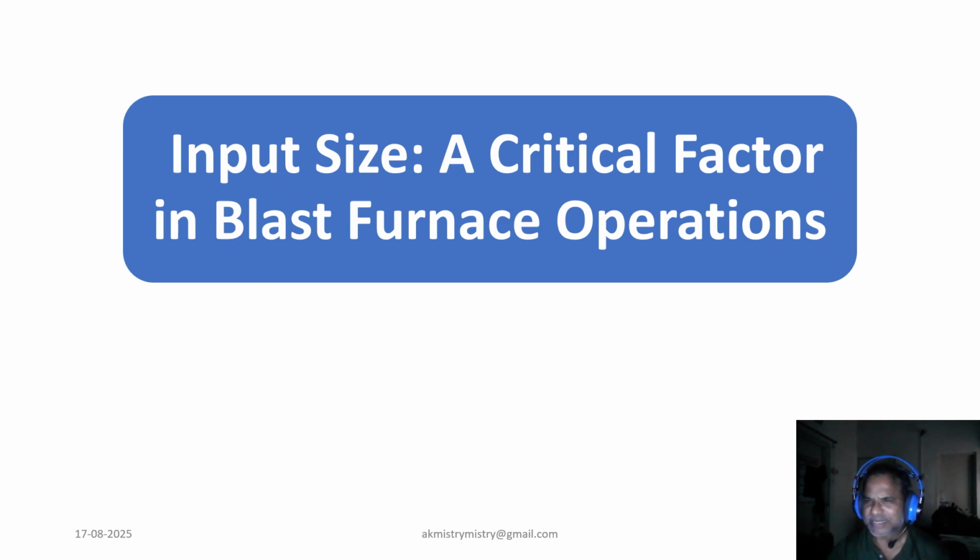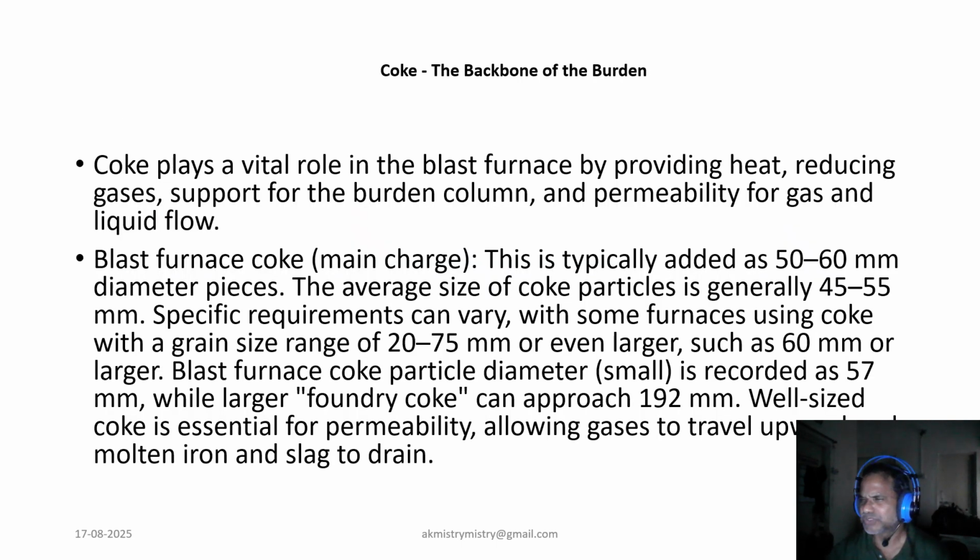Coming to our next slide, which is a most important slide. Let's talk about the coke. Coke isn't just fuel, it plays a multifaceted and vital role in the blast furnace. It provides heat, reducing gases, support for the entire burden column, and crucial permeability for both gas and liquid flow.